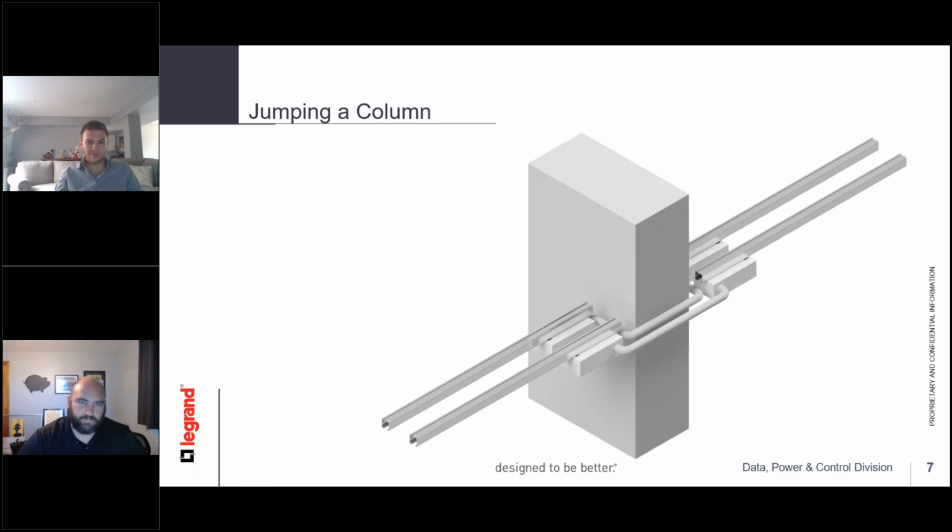We do tend to have to come around air handling systems and columns more often. The applications where I typically see this is where customers may have some data center rows that are staggered 90 degrees off, possibly for a feeder row that they want to connect from one of their other vertical rows. Or if there's additional risers based on how their building's set up, and a customer needs to have an elevation change in their busway. So that's another application for going from either terminal block to terminal block or another end feed to end feed, where that elevation change happens.